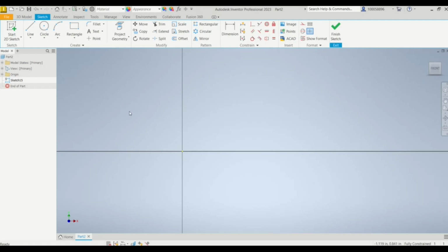So to use that, you have to draw half of that object, of any rounded object. So let's draw a circle, for example 2, and then as I said, we need just the half of the circle to draw a sphere. We use a line to cut it in half. Just click and drag until the other end, click again, and now you have half a circle.